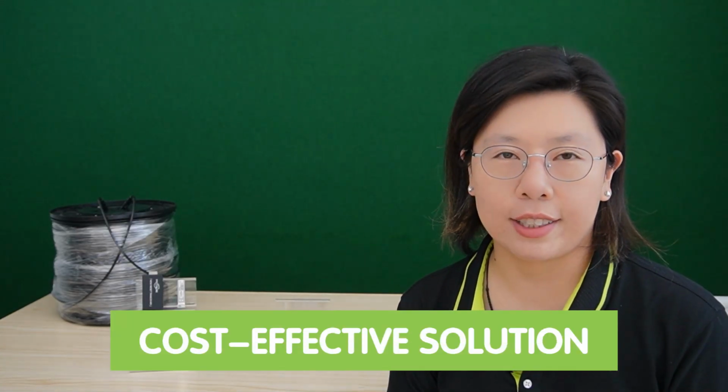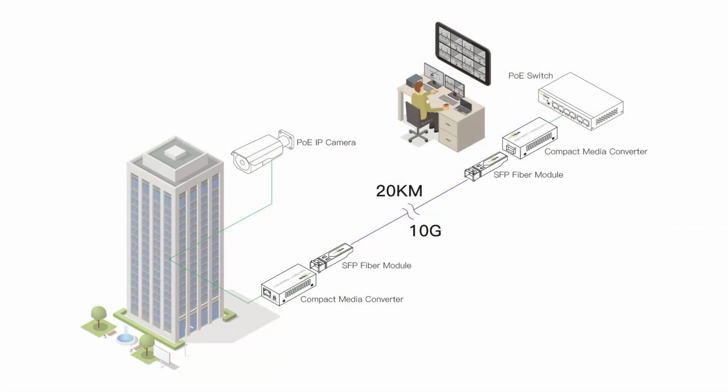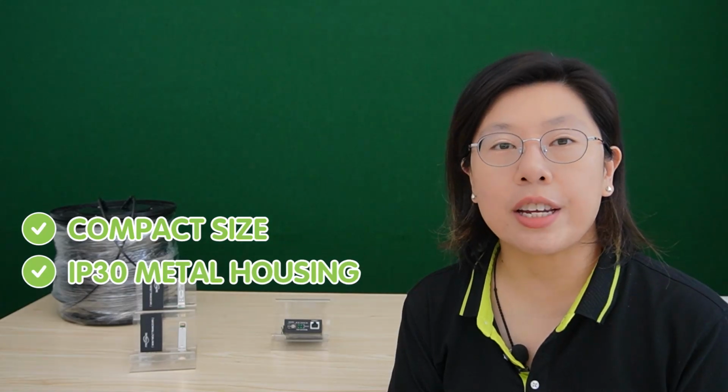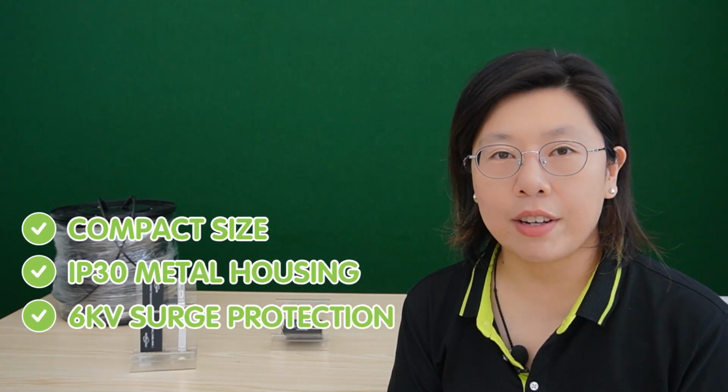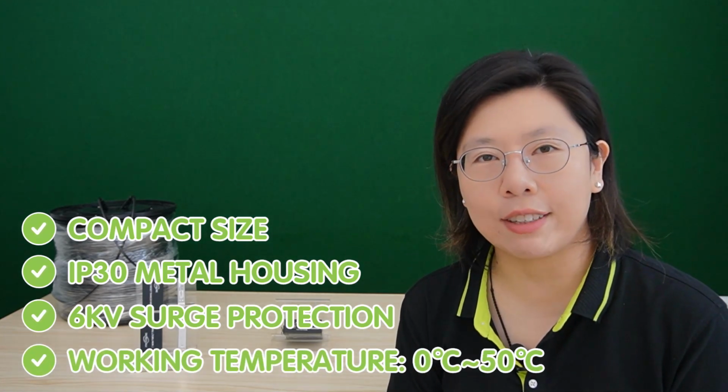It can provide a cost-effective solution to connect Ethernet devices over a fiber backbone and convert the electrical signal into a fiber optical signal, and easily extend your network over 20 kilometers at a lightning-fast data transfer rate of up to 10 gigabit per second over a single mode fiber. It is ideal for a point-to-point link and also works with no problem when mixing 2.5G, 5G or 10G devices. It has a compact size and IP30 metal housing. It also has 6 kV surge protection, and the working temperature range is from 0 degree up to 50 degrees.